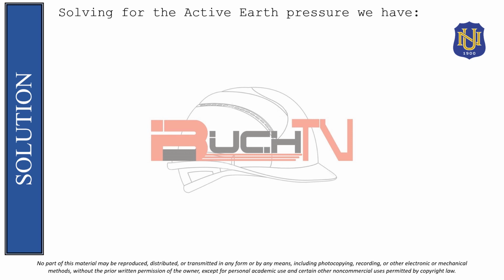So, if we will solve the active earth pressure, we will have P sub A is equal to gamma H times Ka. So substituting gamma, which is 18.4, then 5, we will have P sub A is equal to 18.4 kilonewton per cubic meter times 5 meters times 0.3965.